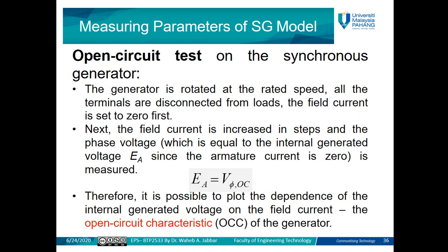So the first test is the open circuit test. For the open circuit test of the synchronous generator, same as in the induction machine or the transformer, when we say open circuit, that means we are not going to connect any load to the machine. In the case of the synchronous generator, the load is usually the electrical load which connects to the stator winding. So in the open circuit test, we are not going to connect any load to the stator winding of the synchronous generator.